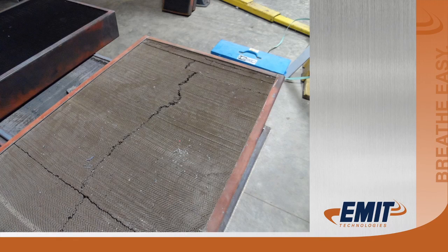Okay. This is a catalyst that came out of a 7044 Waukesha. And this is what happens to a catalyst element. Maybe you weren't running at 1250 degrees, but you were very, very close to it for extended periods of time. Now, on this one, the panel that they had on the unit was not reading the exhaust temperatures correctly.